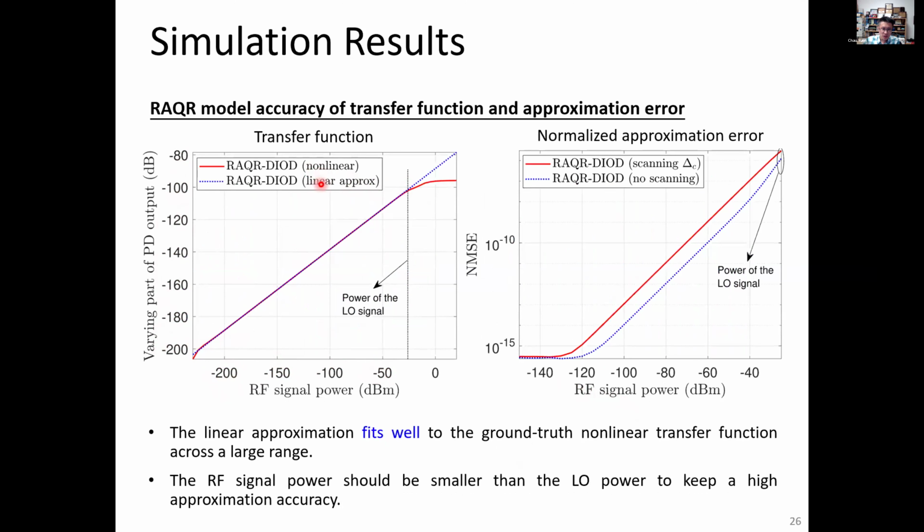But in certain regions, the sensor will have this non-linear behavior. During this non-linear region, we can't approximate using a linear approximation. So this portion we can't approximate well, but over the whole other section, our linear approximation works quite well. Take note of this non-linear portion, because later on when we design the beamforming, etc., we do need to take care of this non-linearity as well. So it's a research problem that we can address.